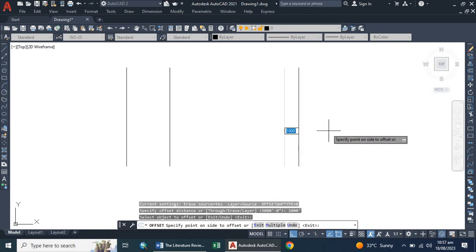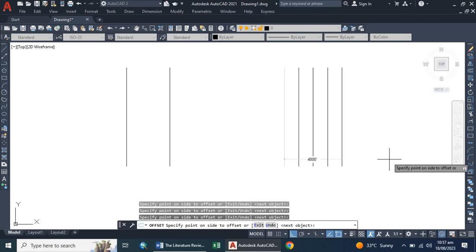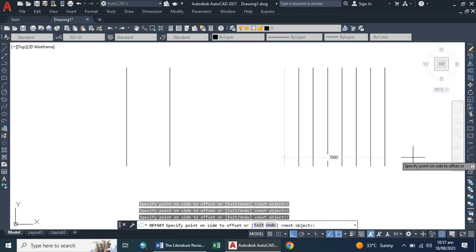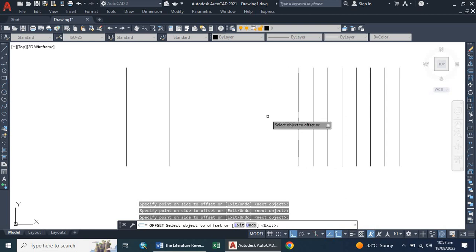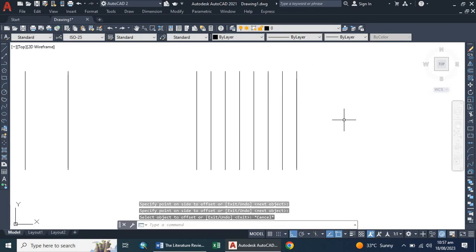I am just clicking on that object, and now if you want to create multiple objects, you will click on Multiple at the bottom and just keep clicking, and your objects will be drawn and drawn, as you can see here. But I have erased my base object, and if you press enter, my base source object will be deleted like that. So I am again going with offset. In this way you can do the operation of multiple offsets.